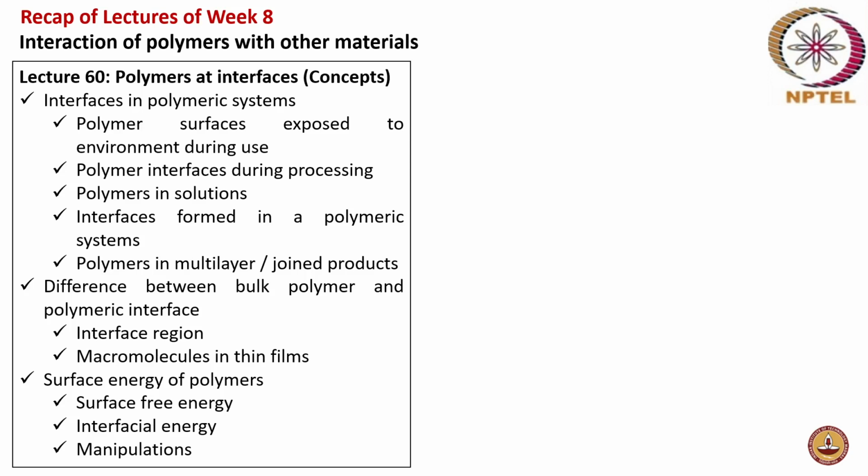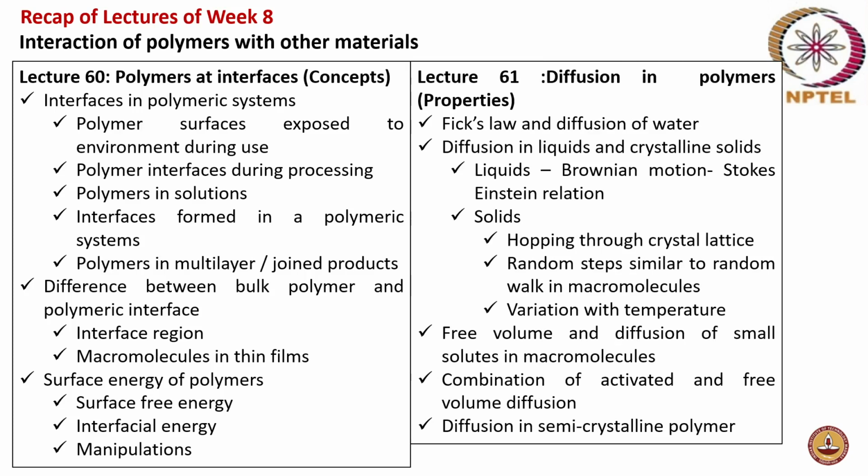Macromolecules in thin films, so in the case of thin films, the interfacial behavior becomes dominant because the thickness of the film itself is very, very small, that more than the bulk behavior, the interaction with the interfacial response becomes much more prominent and dominant in the case of thin films. So this aspect was discussed. Surface energy of polymers, surface free energy, interfacial energy, and what are the manipulations, so these were all discussed.